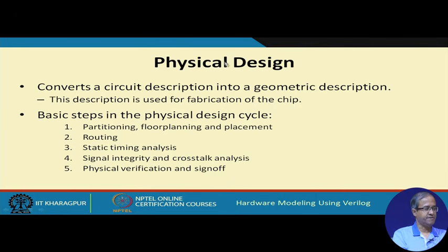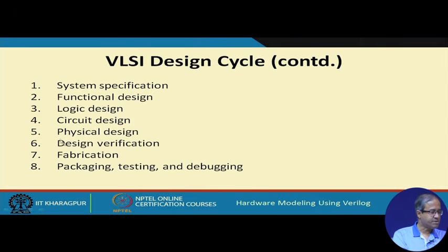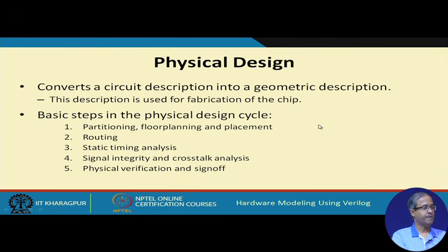Now, talking about physical design, which is somewhere here. After your circuit netlist is done, we go for physical design before you can actually go for fabrication, right. So, physical design roughly says that I start with some kind of a netlist, typically at the gate level or the transistor level, and from the netlist I ultimately translate it into my manufactured hardware.